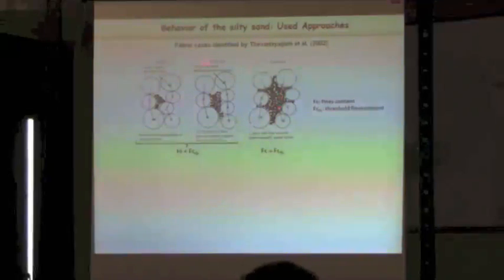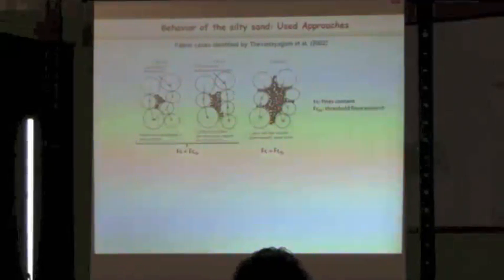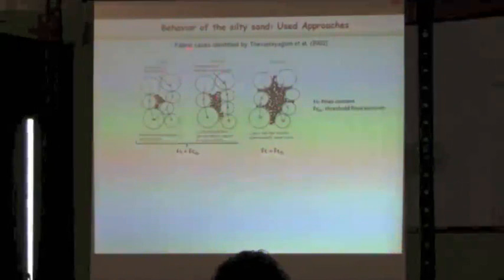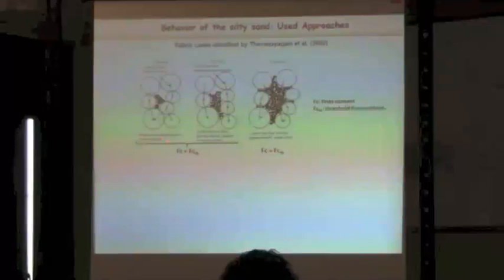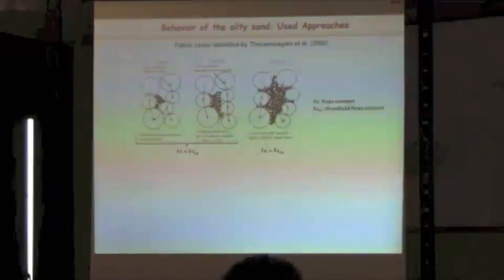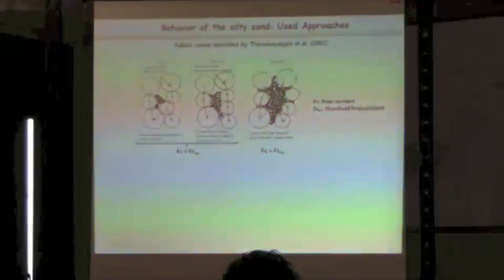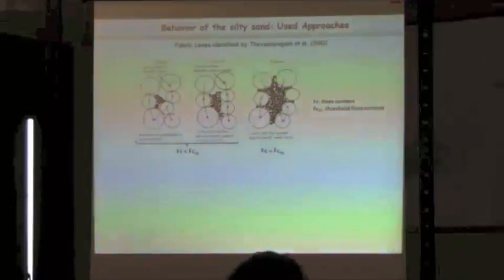In our study we are interested only in the part characterized by a fines content below the threshold fines content. This threshold fines content represents the amount of fines above which the behavior changes tendency. We go from a silty sand structure to a sandy silt structure. To study this type of structure, the use of the global void ratio appears inappropriate.